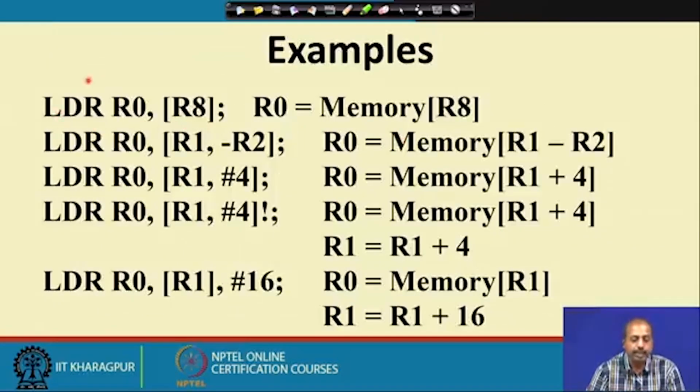The LDR instruction stands for load register. LDR R0, [R8] means register R0 will get the content from memory location R8. This is indirect addressing.